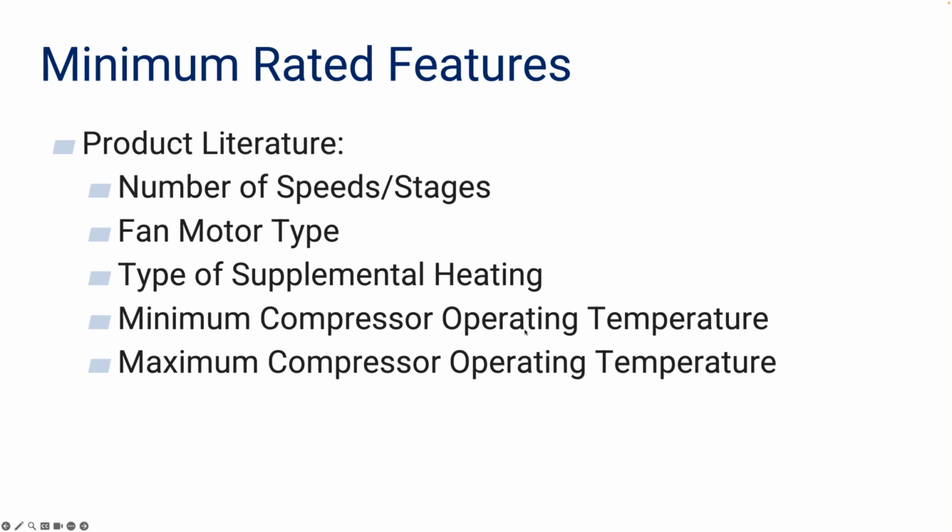We have the minimum compressor operating temperature, and this is usually found in the product literature. For single and two stage equipment, we assume that if you can't find it in the literature, there's a default of 0 degrees, and for variable speed equipment, which is targeting more cold climate applications, we use a -20 minimum compressor temperature.